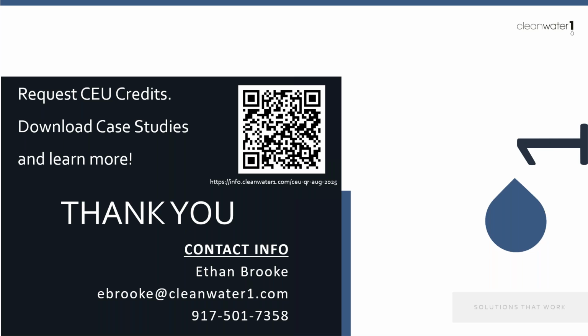There's an equation that we use to model the effective water temperature on Henry's constants. Also on the topic of temperature, important to note, I got a question from a consultant on this not too long ago. What about air temperature? Well, we looked at this fairly exhaustively in that peer-reviewed paper that I published back in 2011. We did not find any evidence that air temperature has an effect on overall removal rates. Water temperature does, air temperature does not.